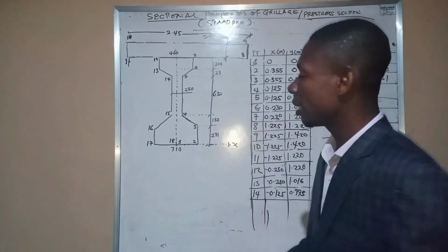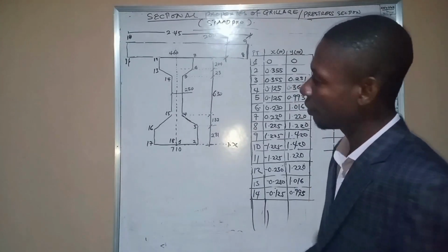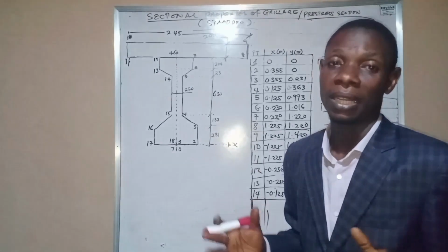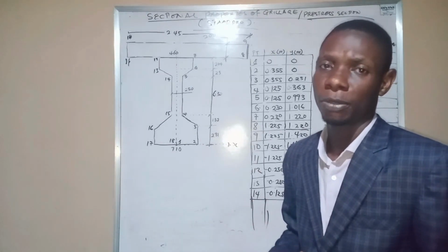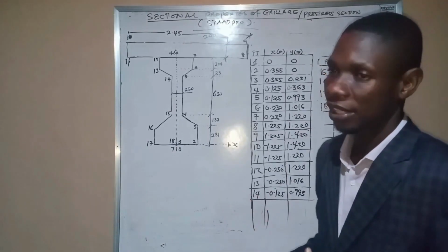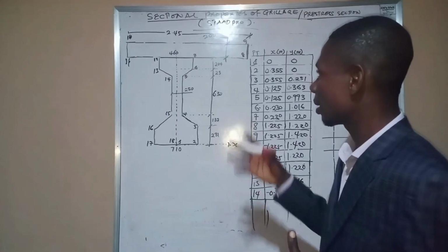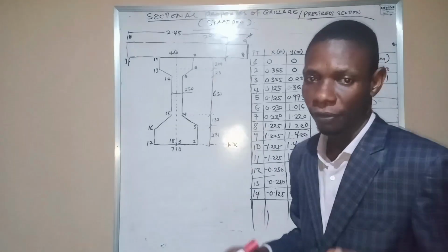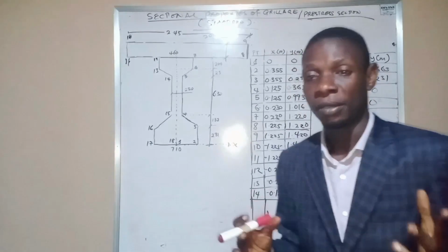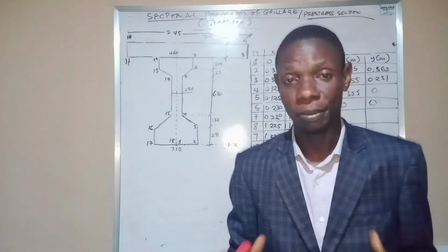So we are going to apply this, and we're going to see how we can generate these sections. Now, alternatively, if we decide to design this section manually, probably using the orthotropic plate method, of course, we can decide to go for additional sections. For example, we need to get the edge beam. Of course, for you to design using the orthotropic plate method, you must convert this beam, this deck section, into an orthotropic plate.